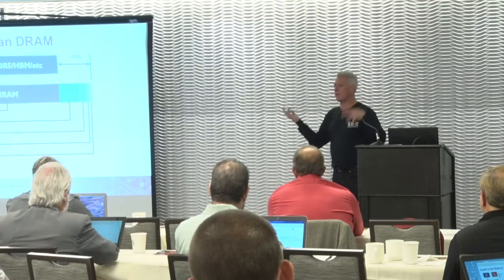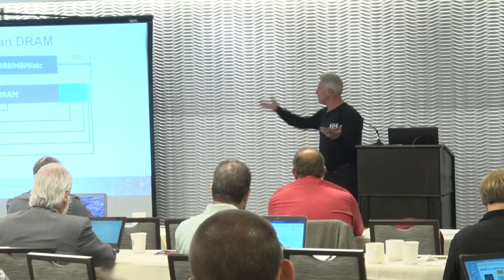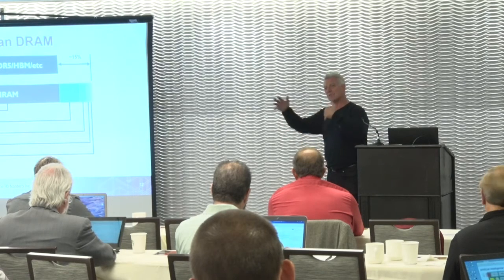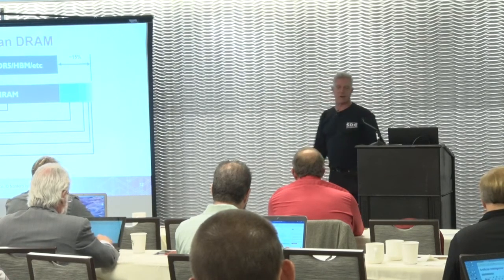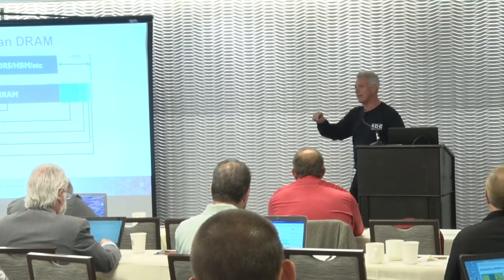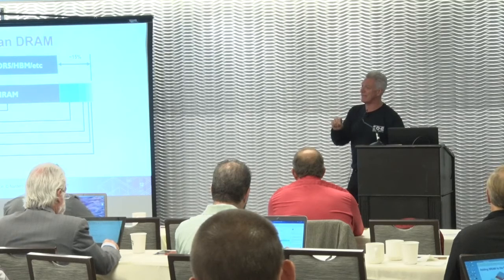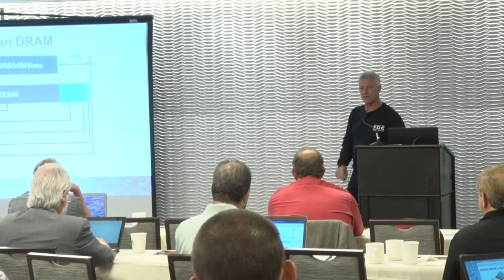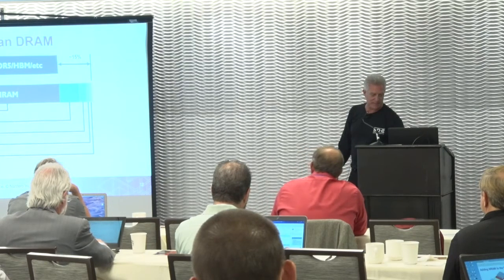Bank groups. We don't have bank groups. We're emulating that bank group structure. We have the same timing all the way across the chip. We don't need bank group timings. You start adding these things up, and you can see perhaps as much as 20% additional data throughput at the same clock frequency as the DRAM, while being in a compatible footprint and application space.